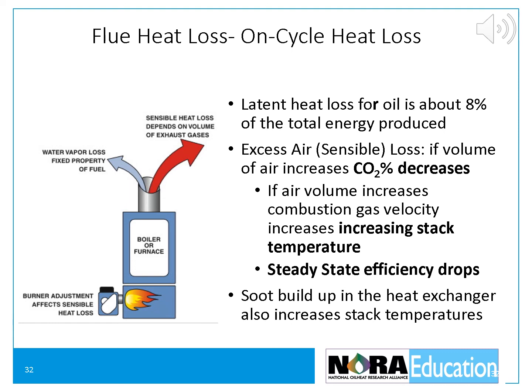Combustion air normally enters the burner at basement air temperature, which is usually about 63 degrees. The exhaust gases at the breech are normally between 350 and 600 degrees. The heat in these gases that goes up the chimney is heat loss. Some loss is unavoidable, but heat loss can be reduced by better burner air adjustment, clean heat exchanger surfaces, or equipment replacement. New equipment uses much less combustion air, and some units do not need a draft regulator, hence less heat flow up the flue.